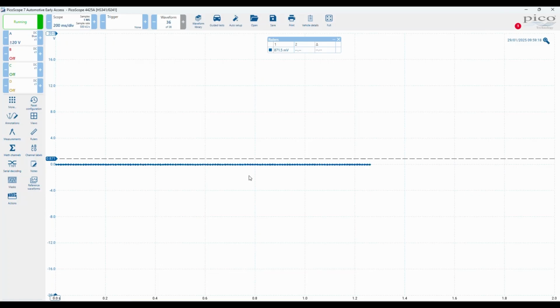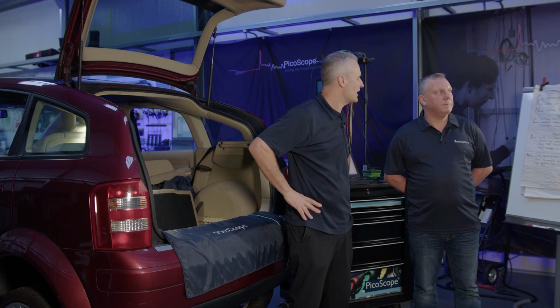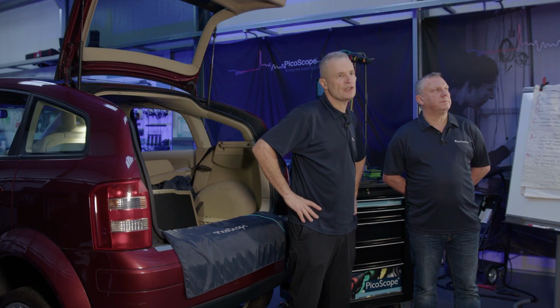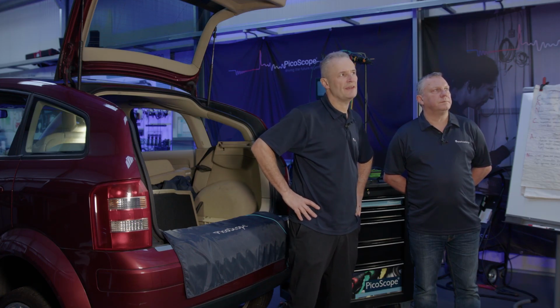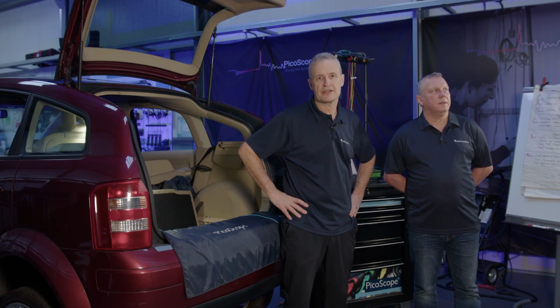And let's pull that right down to 0 volts. In fact, you could see earlier on how that was starting to dissipate anyway, but we'll leave that on just for a few seconds. We can be assured now that this vehicle is truly at 0 volts and shut down, so we can proceed with the next test.